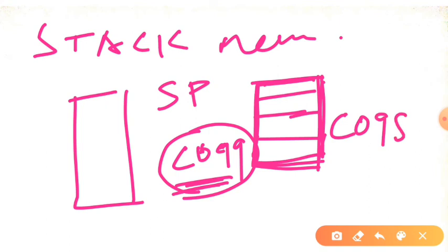So this is the top of the stack. If you want to store something, the first thing you need to do is decrement the address stored in the stack pointer. We will get the next memory address C098, and here you store something. Suppose we are storing some random value EF over here. Again, if you want to store something, we need to decrement the address of the stack pointer, which is right now C098.